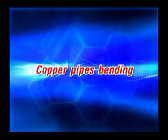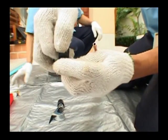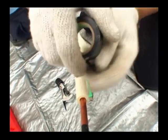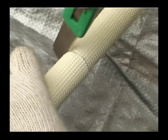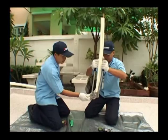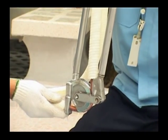Copper pipes bending. It starts with sealing both ends of the pipes completely with wire tape to prevent foreign substances from entering the pipes. As they are ready-made pipes, use a cutter to cut their seal. Then use a bender to bend the gaseous refrigerant pipe and the liquid refrigerant pipe to suit the installation location.